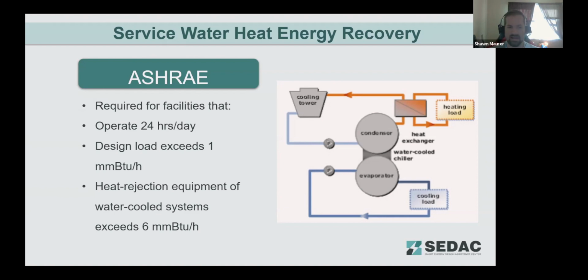Not likely to apply to a lot of facilities, but where you've got 24-hour operation and a large load for domestic water on a continuous basis, that's where this requirement is triggered. You're mainly looking at hospitals or larger facilities that include residences, where people are constantly in that facility. You might also consider using heat pumps, either air source or water source, even if not required.